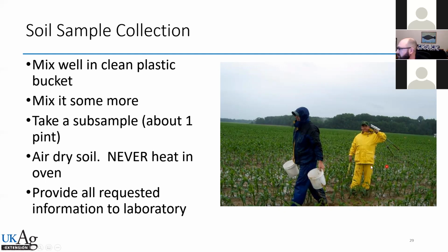Don't sample when it's soaking wet like this unless you're doing research. And if you do have to take a wet soil, because it seems like it's rained every day in the past 5 years, so I understand, but don't put the soil in the oven. Don't leave it on the dashboard of your vehicle where it's going to heat up in the sun while it's soaking wet, because funky stuff starts happening.